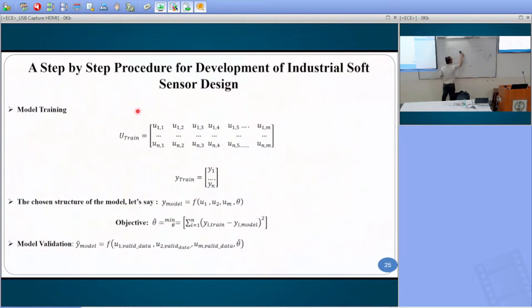You can do the same thing if your model is an auto-regressive model. The model just changes: it will be a times y(k-1) plus b times y(k-2), c times y(k-3), and so on for as many past features as you are considering, plus u(k-1), u(k-2) and so on. These are past outputs and inputs. So use the same model and do the parameter estimation. It's the same process as for the simple regression problem, but you get additional features, which are the past values of your output and input.